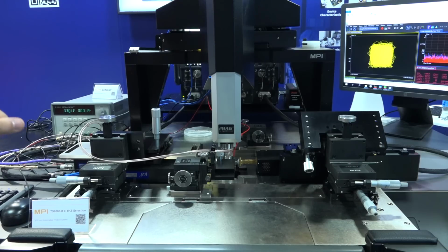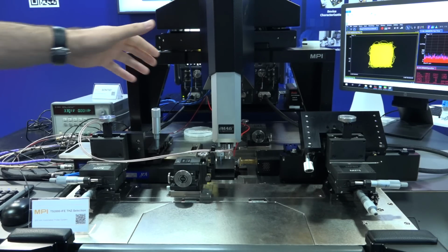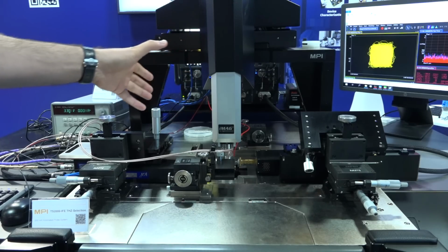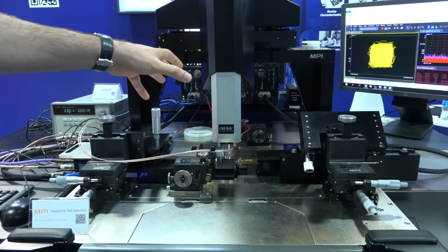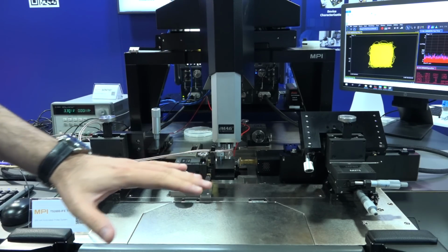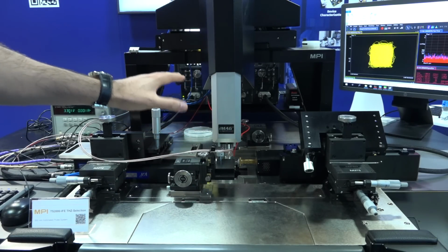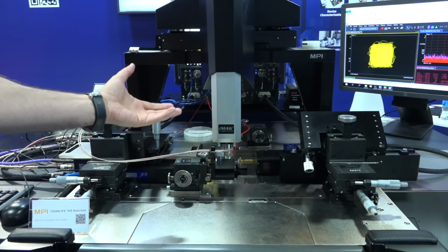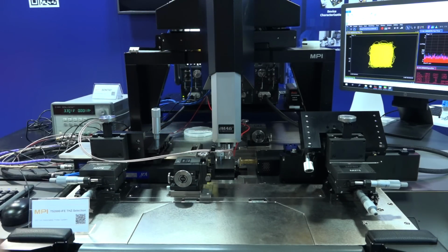Now, there's a few unique features about the way this probing system actually works, is that it supports down to minus 60 degrees Celsius directly in an open environment. And they do this by making sure that there is appropriate laminar airflow above and below where the chuck is cooled down so that you don't get any frosting and you don't get any condensation.